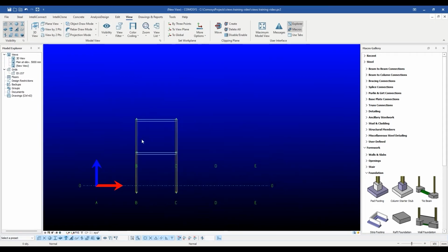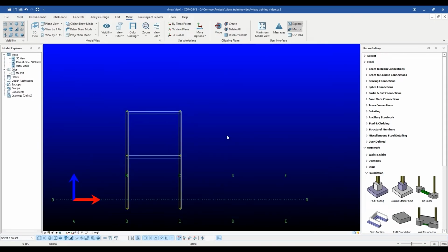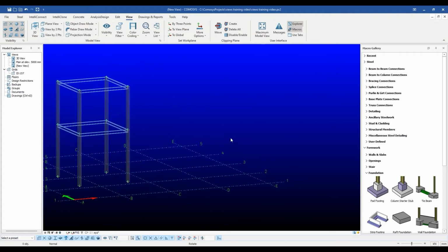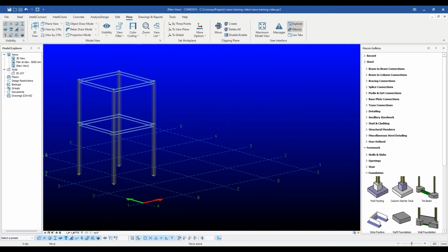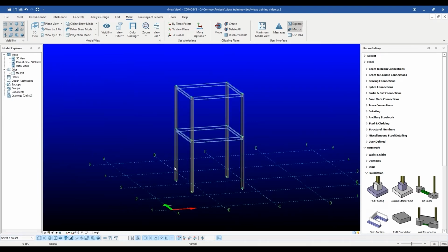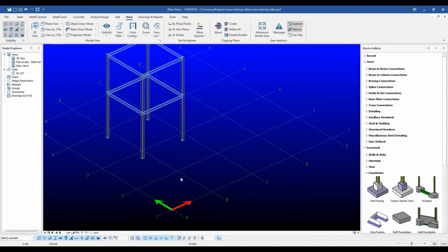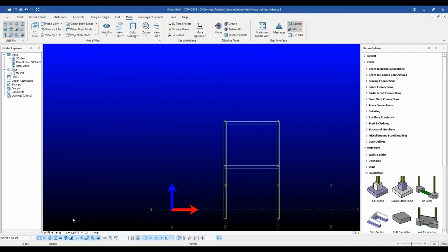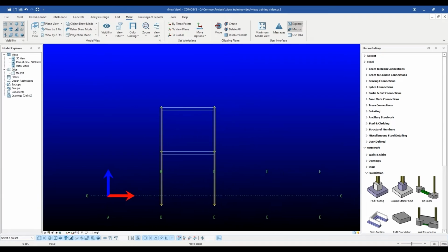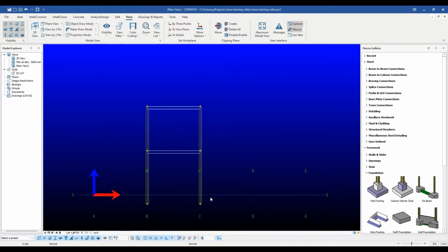After creating a view, we can still rotate it by pressing the right mouse button and make it look like any 3D view. But this does not change the original definition of the view. The moment we press this 0 button at the bottom of the view, its original orientation is restored. This is called zeroing the view, and snaps work differently in zeroed views and non-zeroed views. We will talk about them later.